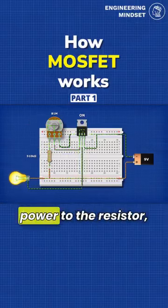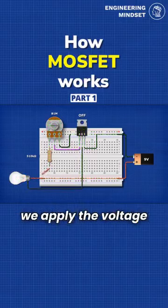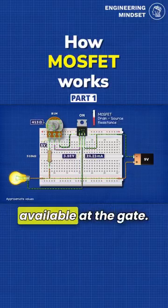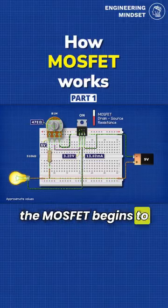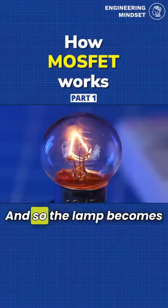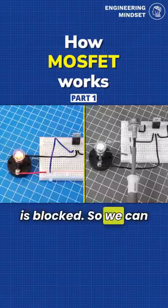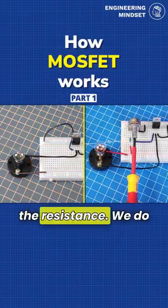When we disconnect the power to the resistor, the MOSFET drains through the potentiometer. If we apply the voltage again, we can rotate the potentiometer to increase the resistance. That reduces the voltage available at the gate. As the gate voltage reduces, the MOSFET begins to deactivate, increasing the resistance between the drain and source. And so the lamp becomes dimmer and dimmer until the MOSFET completely deactivates and the current is blocked. So we can turn a circuit on and off, or we can vary the gate voltage to vary the resistance.